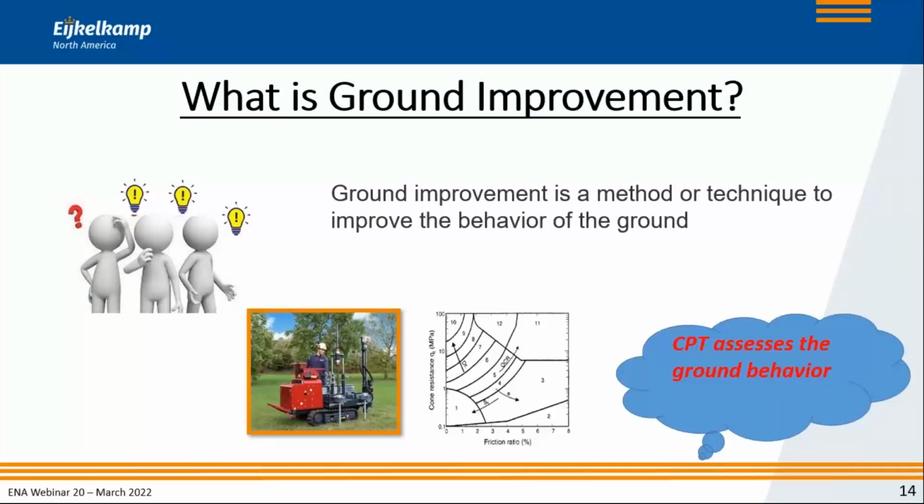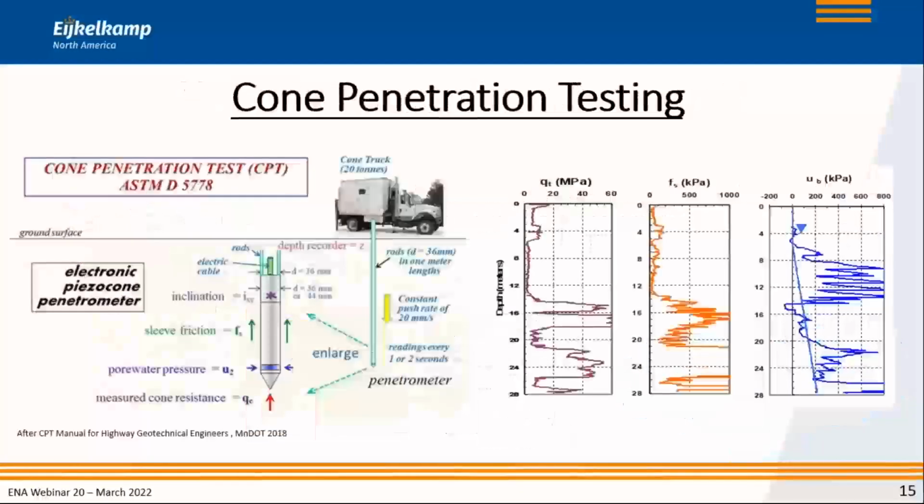And then, of course, the graph that you see now at the bottom of your screen has everything to do with it. Because for those of you that are not that familiar with CPT, as you push the cone into the ground, you get those three squiggly lines, as Paul Main refers to them: the tip resistance, the sleeve friction, and then the pore pressure.